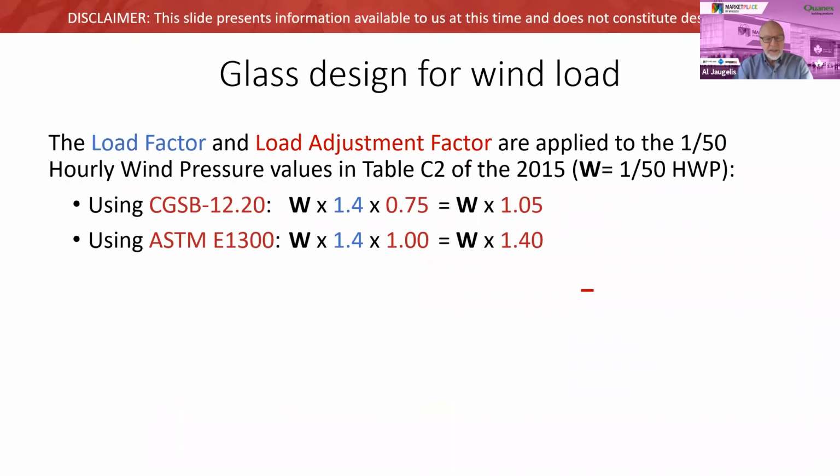So here's what that looks like. Actually, Al, first those were factored per A440.S1, right? Pardon? So it's not the hourly wind pressure that enters into that equation. It's that times the adjustment factor and the exposure coefficient and the internal and external gust factor and pressure coefficients. Right, but don't these factors get applied before you do those calculations? That's right. Yes.